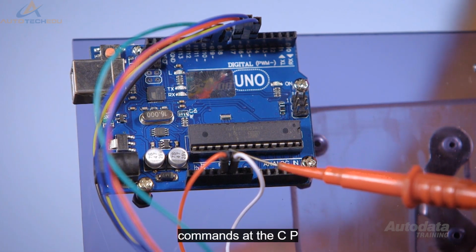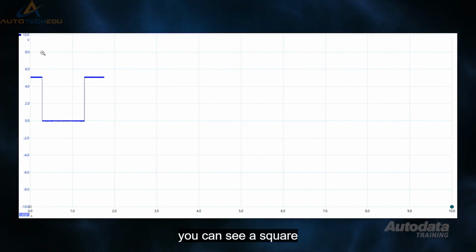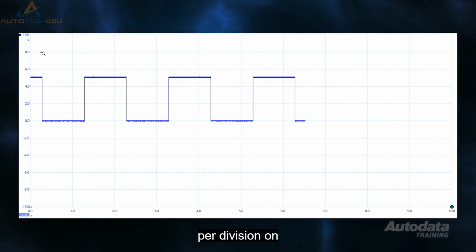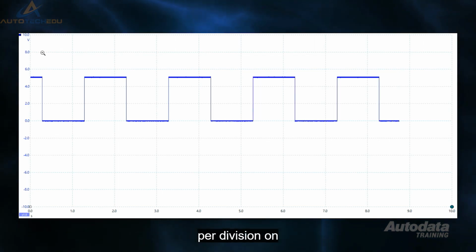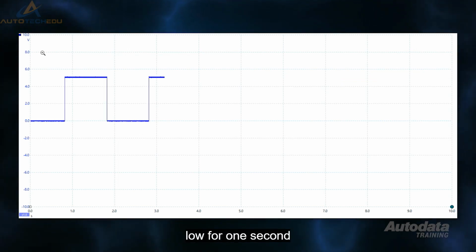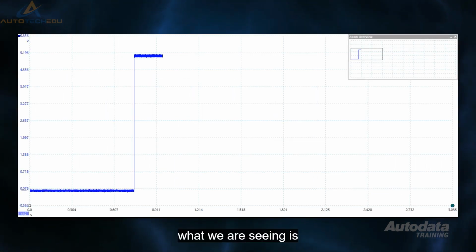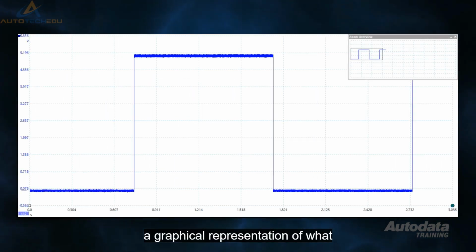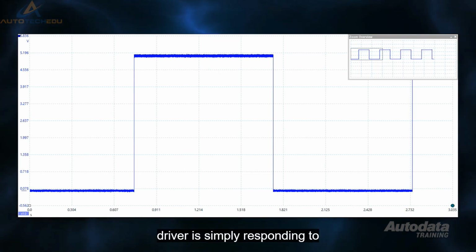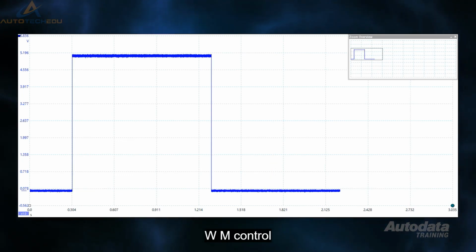Let's look at some digital commands at the CPU with an oscilloscope. You can see a square wave pattern on the screen. The time base is set at 1 second per division. On this trace, the processor is pulling the circuit high for 1 second and then low for 1 second. This is 1 cycle. What we are seeing is a graphical representation of what the software has been programmed to do. The output driver is simply responding to the high and low commands, resulting in a PWM control.